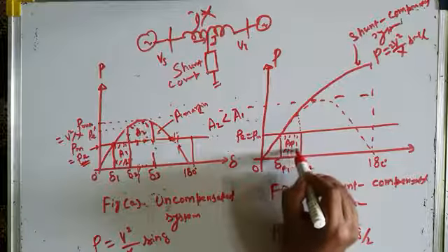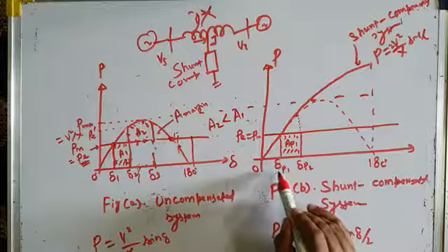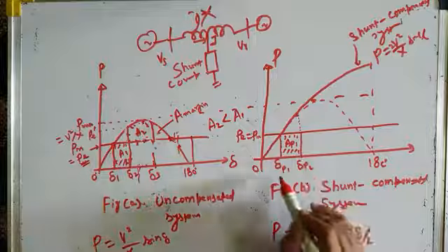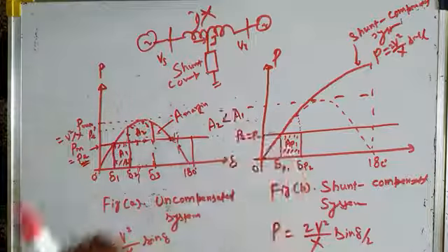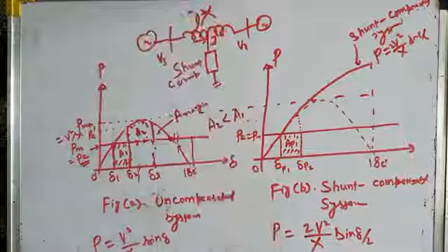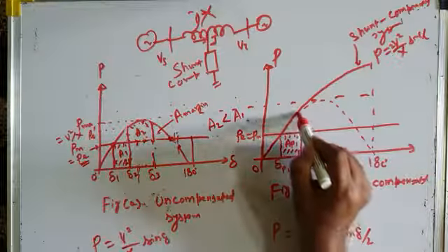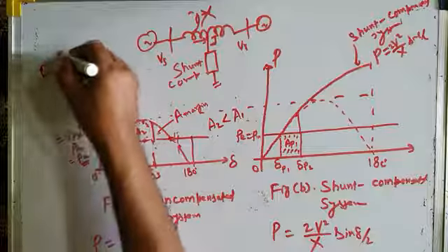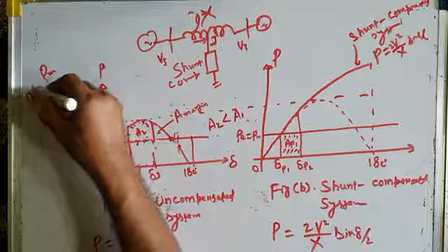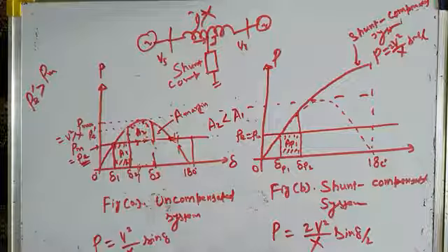which represents the accelerating kinetic energy. And as the transmission angle increases because of acceleration of the machine from delta P1 to delta P2, we assume the fault is cleared and the line is reconnected. It again starts transmitting power, but how much power will it transfer? It will transfer higher power. So mechanical input is the same, electrical output is higher, PE dash is greater than PE, and it is greater than PM. So the machine starts decelerating,